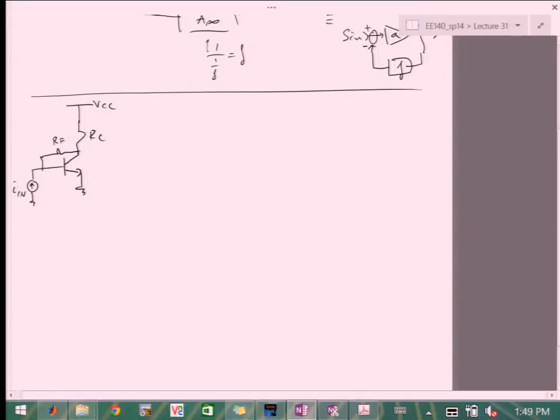Okay. So we're going to do the same exact thing that we did a moment ago with A equivalent, right? So now we're just looking to find A infinity. Because we have the return ratio, we have A0. So this is the only missing piece, if we don't want to do the A equivalent. So for this, we're going to set K to infinity, which means that GM goes to infinity.